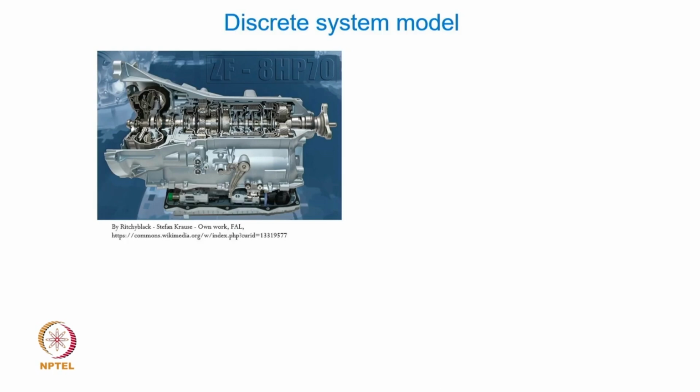It is not going to be 2 or 3 or 4 or 5 degrees of freedom, it will definitely be in excess of at least 10 of them. The shafts also have different cross sections all through. You can see that the cross section of the shaft will continuously change and vary at different locations. So, this is one example where you might like to model this as a system where properties are continuously changing.